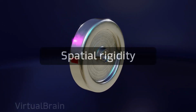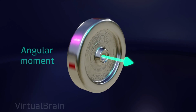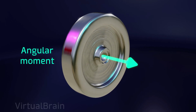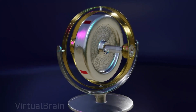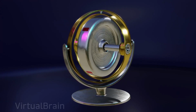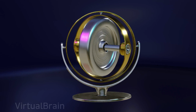The first application makes use of the spatial rigidity of a rotating object. If we rotate a disk at a certain angular velocity, and there are no other forces that generate any torque on the disk, its angular momentum will be conserved. Because of this, it will continue to rotate on the same axis and therefore maintain its orientation. This was used by Leon Foucault, who mounted a disc on a cardan suspension or gimbal, which allows free rotation of the centerpiece. In this system, by rolling the center disc at a high speed, or in technical terms, applying a large angular momentum to it, its orientation will not change, even if the rest of the system does.